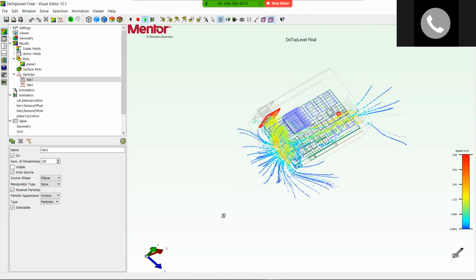I don't know if you know this, but in a typical rack mount system, right, the two boards on the side are the ones that get the most of the heat, and the board in the middle are the coolest one. Now, how much hotter, how much cooler, that requires an analysis. And with the parametric analysis, you can decide what the spacing between the boards are, okay, to figure out what is the optimum spacing of the board in the slot, things like that.